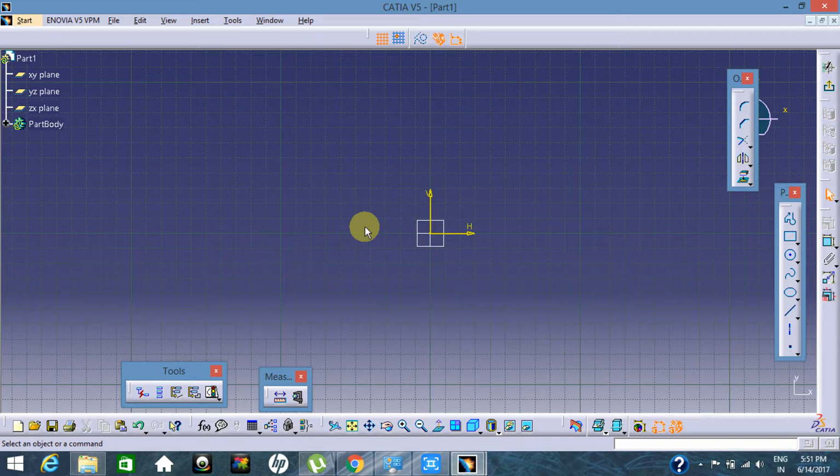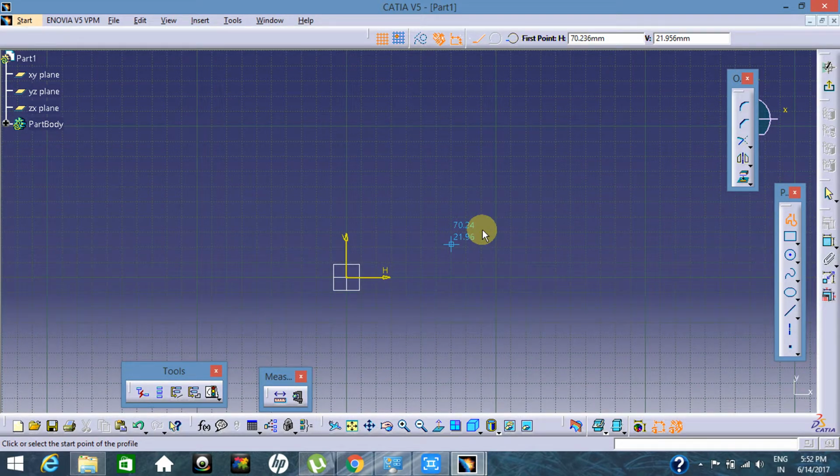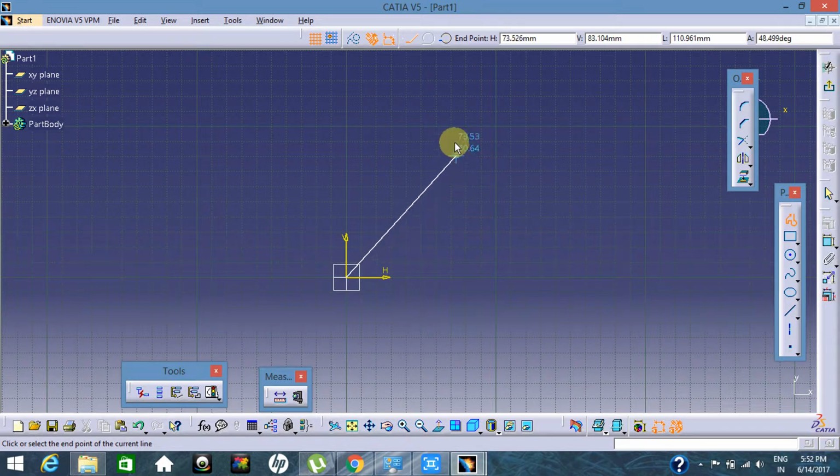So if you want to create multiple continuous lines, just click on the Profile icon. You can see a Profile icon here. This Profile icon helps us to create a continuous line without any discontinuity. So when I click here, you can see the Sketch tools have some more options here. Just forget it for the first time, and this tool is now asking for your first point. If you want to start from the origin, just click here for the first point and then click on the second point wherever you want it.